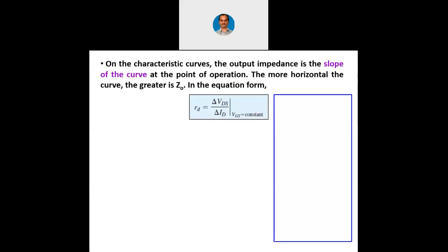The saturation region is the region where the JFET is operating in the quiescent conditions, whereas the ohmic region corresponds to completely on condition and cutoff region corresponds to completely off condition. Now we are going to measure this drain resistance basically in the saturation region or during the quiescent conditions. So that is delta VDS by delta ID. If you recall the output characteristics, you will remember that in the ohmic region, it is like a straight line. There it is also called the linear region.